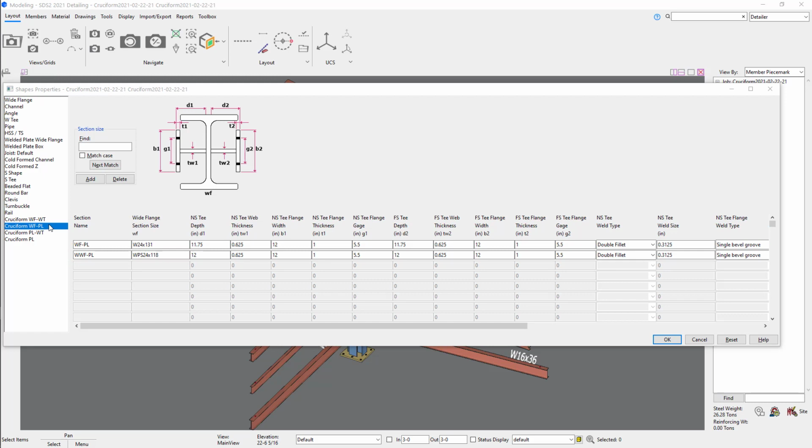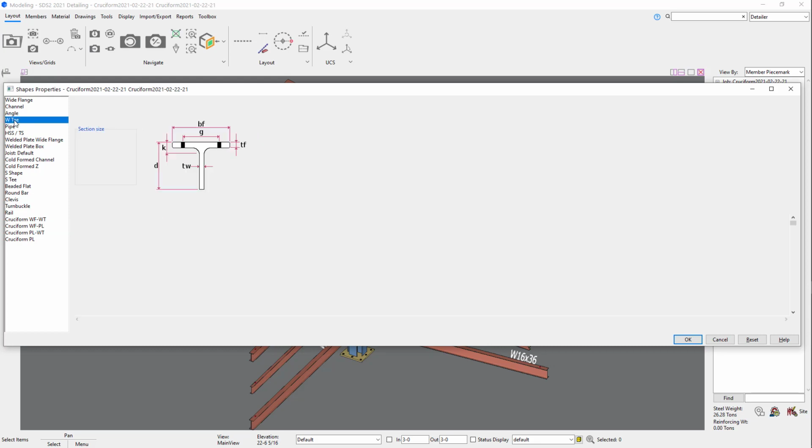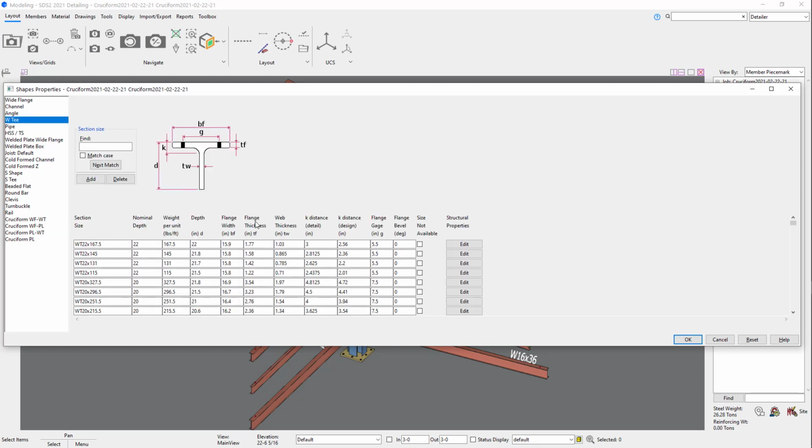One caution about selecting welded wide flanges is that you will not get the weld between the flange and the web. Selecting cruciform plate would be a better option. For WT sections, if you cut them from a wide flange, you will want to adjust the stem depth of the WT in the WT material type.